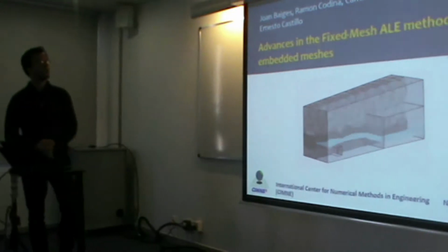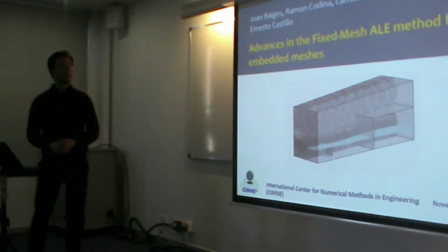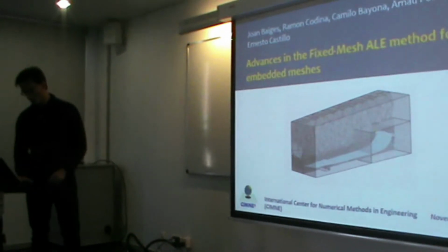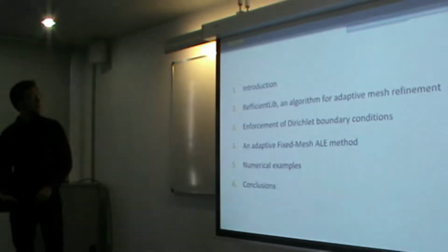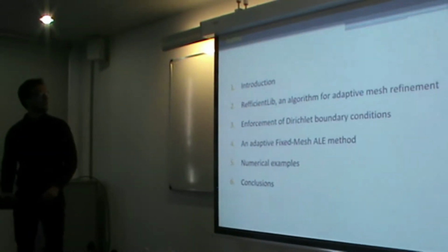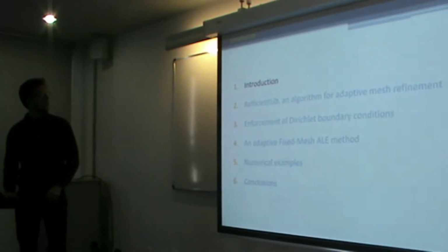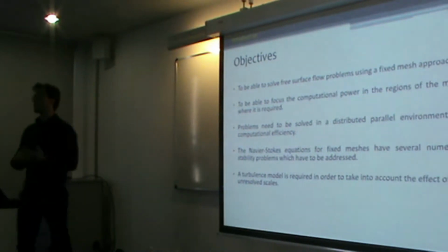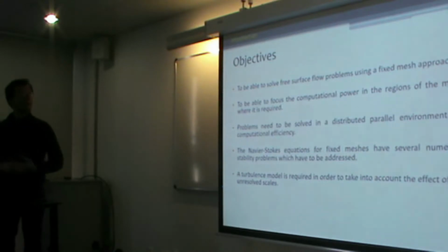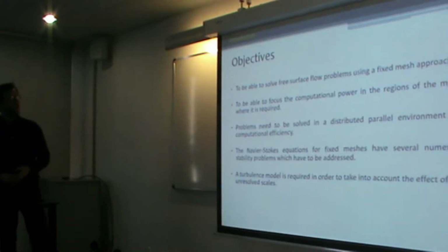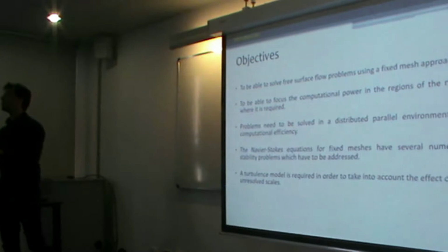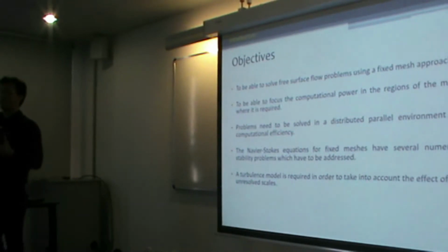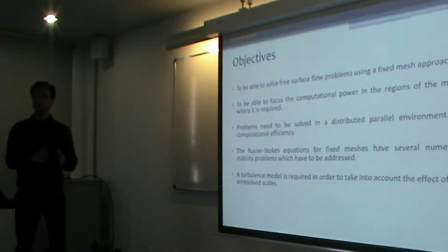Methods that we have developed for the fixed mesh ALE method for embedded meshes, and in particular for free surface flows. Okay, so this is the outline of the presentation. The idea is that we want to be able to solve free surface flow problems by using a fixed mesh approach. And we also want to be able to focus the computational power that we need in the regions where it is needed. Okay?